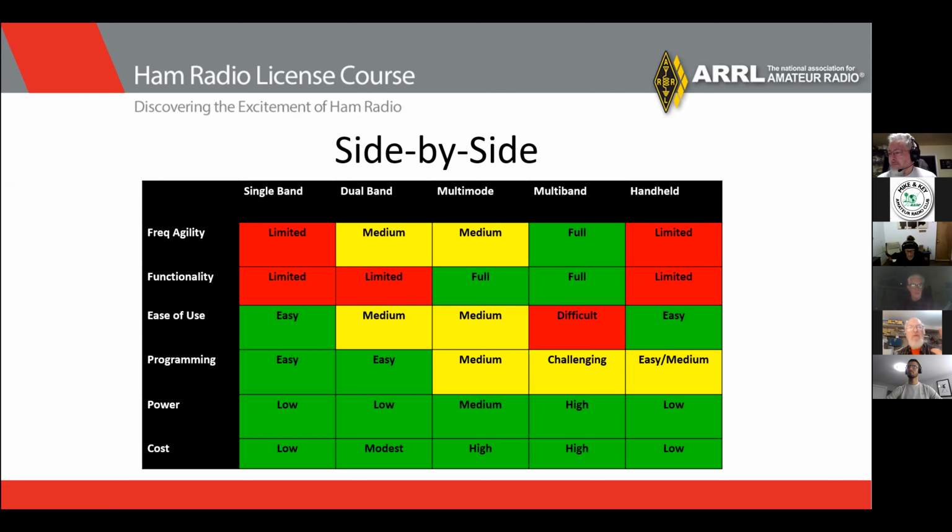So you get the right tone, and then make sure the tone's turned on. So 1, 2, 3, 4: get the dial frequency, make sure your offset's correct, the correct tone's in memory. That's why it's nice to have these radios pre-programmed. And make sure the tone's on. 1, 2, 3, 4. Then when you push the button, the chance of you talking to that repeater, if you can hear it, is almost 99%.